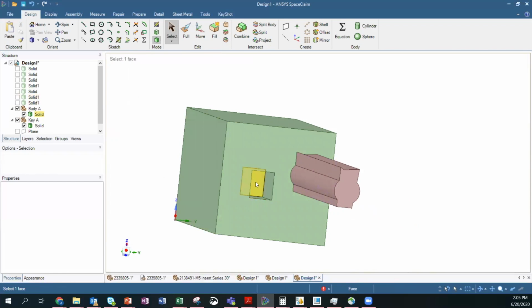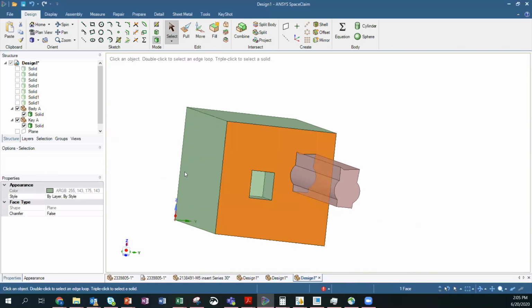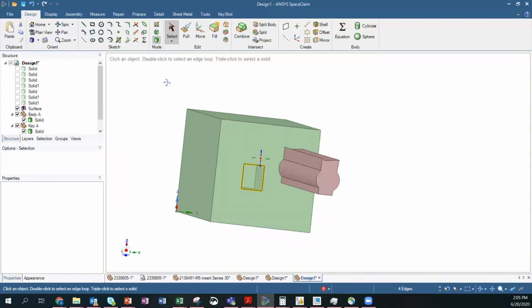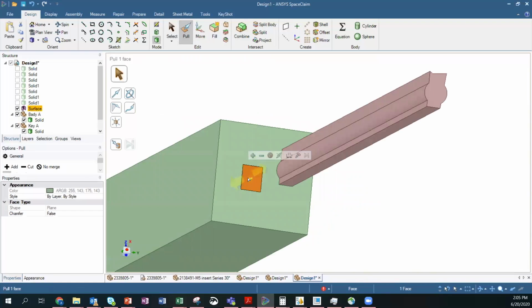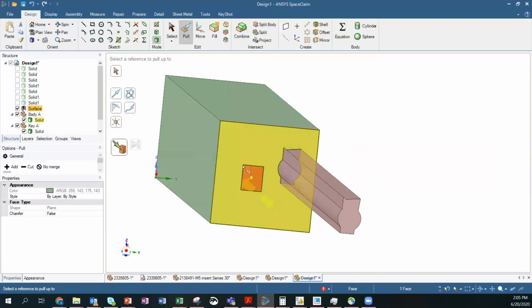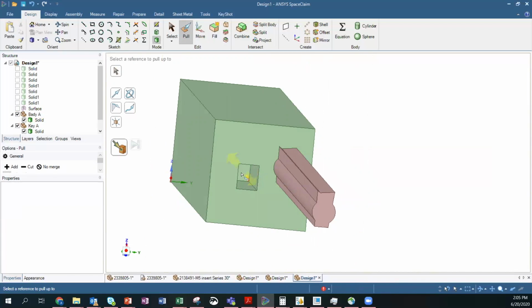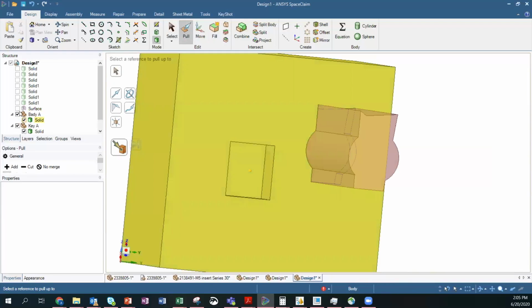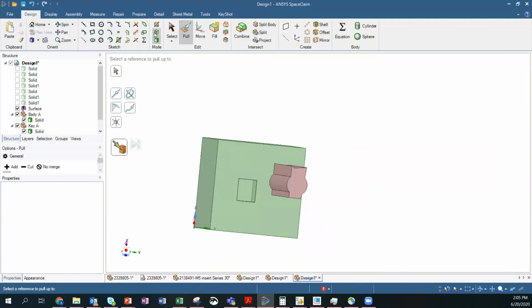Say I just want to make a key even here. All I have to do is click on the circumference, double click on it and fill. This is a trick, and you just choose the body. See, right now I want to select the surface inside, but it doesn't let me do it. So I just hide it, and it doesn't let me. Okay, then I'll do a cross section.